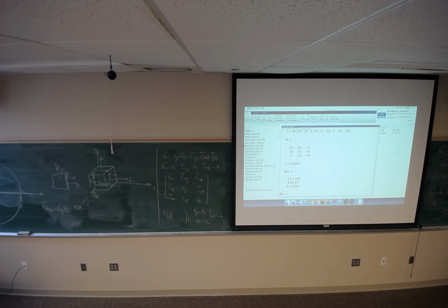If you have a plane stress element like the previous example that we did, one of the principal normal stresses always would be 0 because we have plane stress. For this one also you can draw a 3-dimensional Mohr circle. Sigma 1 here it's 10. In this example sigma 2 is 0 and sigma 3 is negative 10.